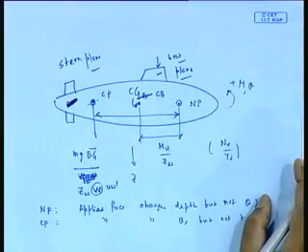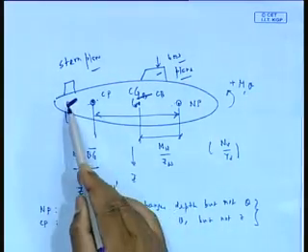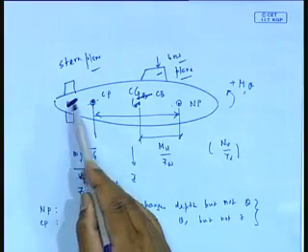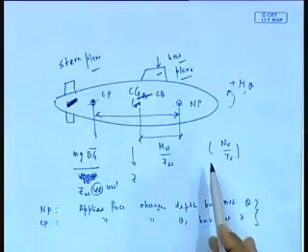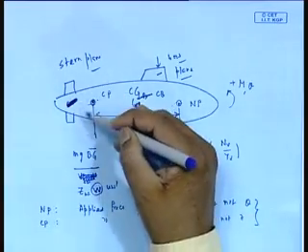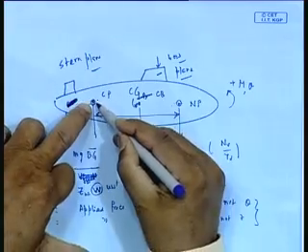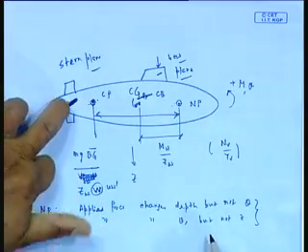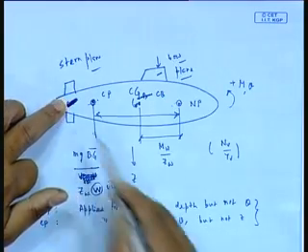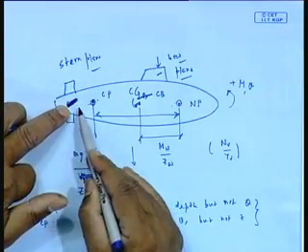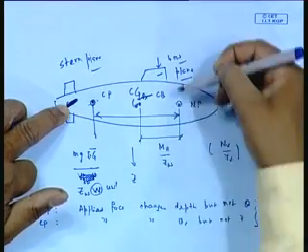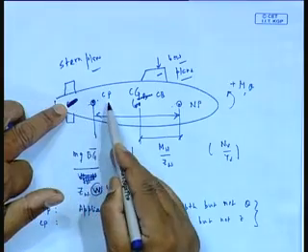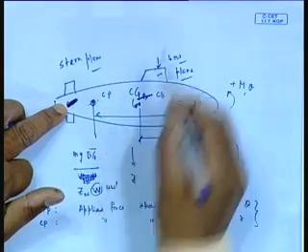Now, the point is, if this is aft of Cp, when I turn it to go down, what would happen? The force applied at this point gives no change in depth, but if you make it aft, one can show that there is a change in depth in one direction, it goes down. But if this becomes forward of Cp, then it goes up.